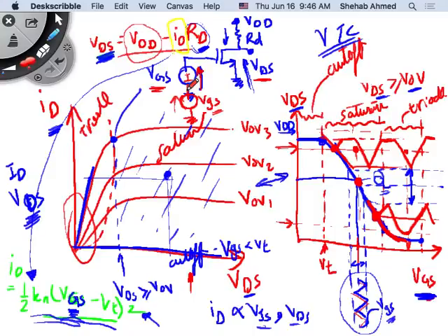And then we can do it all together, DC operating point and AC small signal, or we can split them. If we split them, then we utilize superposition. Superposition means the sources in my DC operating point I will make 0. I will short them. So my VDD will be 0, and my capital VGS will be 0. I will only be left with small VGS, and that will be a small signal input to a model. So there are many ways. The stuff that we will not cover is elaborations on that, after we split.